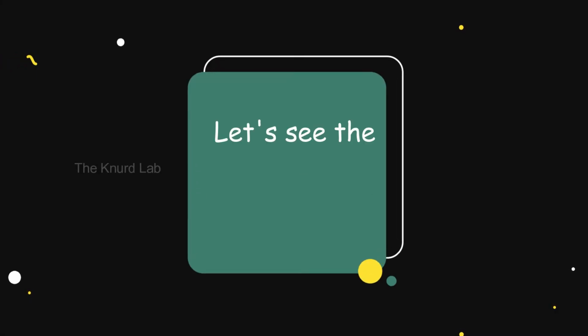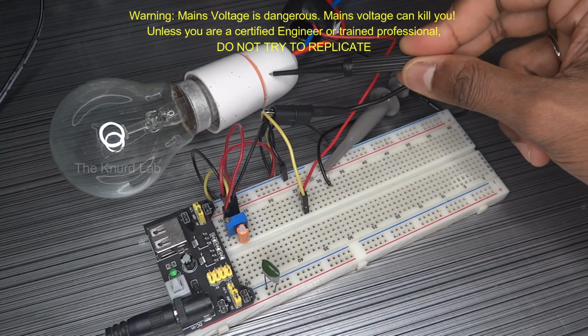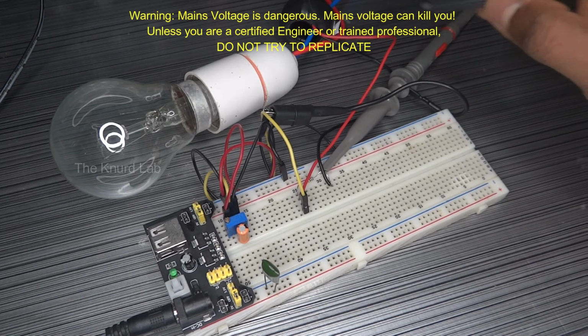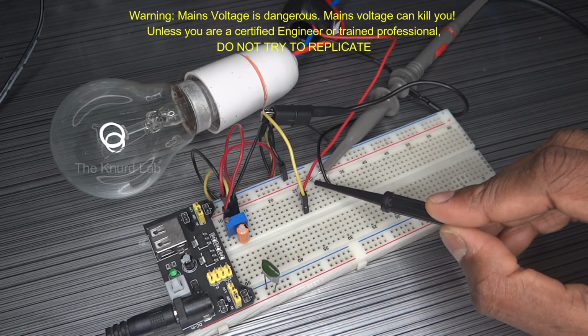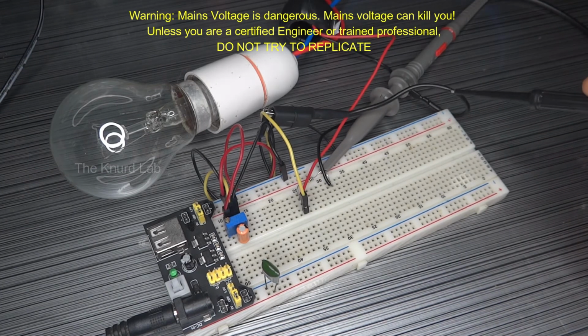Now that we have designed the circuit, let's quickly put everything together and see it in action. I have used a 60 watt incandescent light bulb as the load, which is powered by 220 volts AC supply. The current transformer with a burden resistor of 56 ohm is used to measure this AC current. I have connected an oscilloscope across the output of the burden resistor and the ground.